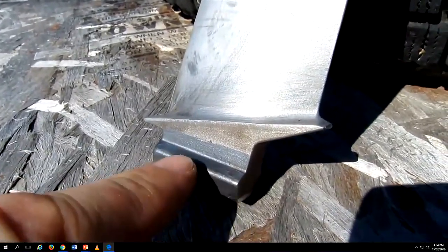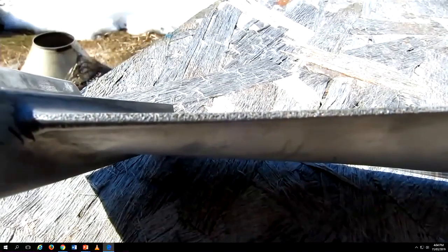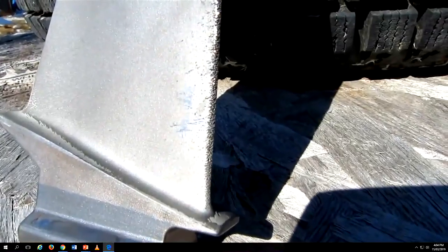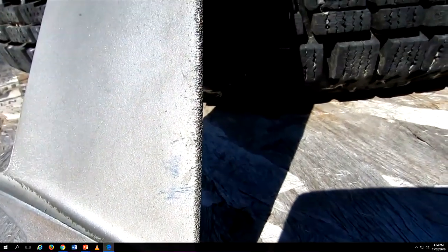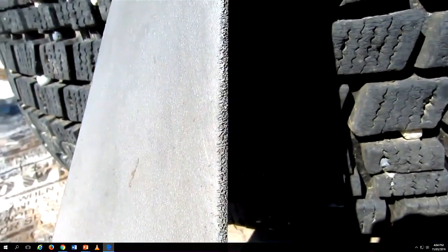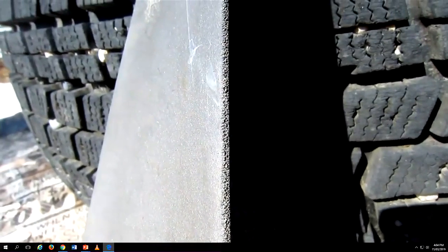There's another very good example of what happens. This can't be repaired. What can be repaired, up to a limit, is the leading edge of the compressor rotor blade. You see that rough texture with all the little pits and holes and moon-like surface? You see that leading edge? All the pock marks from tiny particles of solid debris, sand or dust, smashing into that at very high speed. This is a solid stainless steel blade, so you can get an idea of the energy and the speed of this thing.